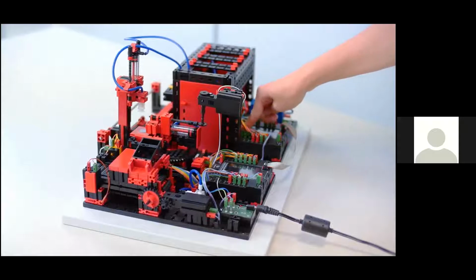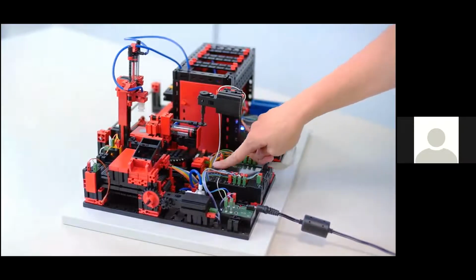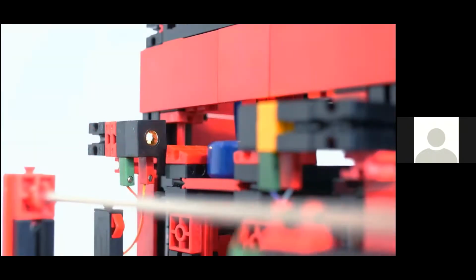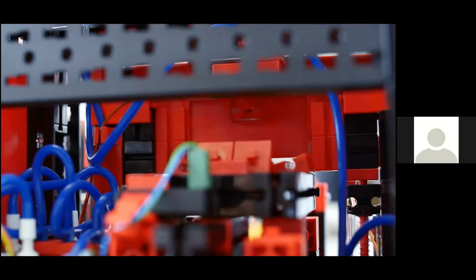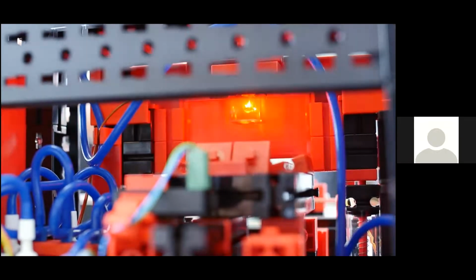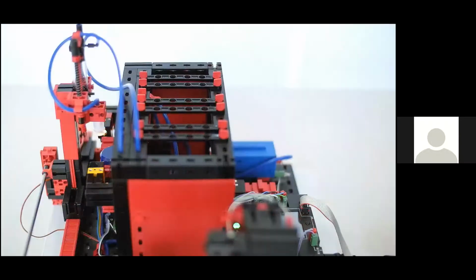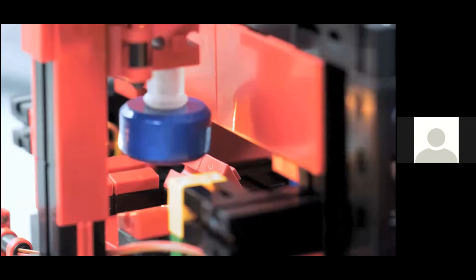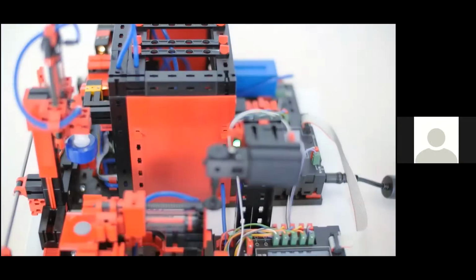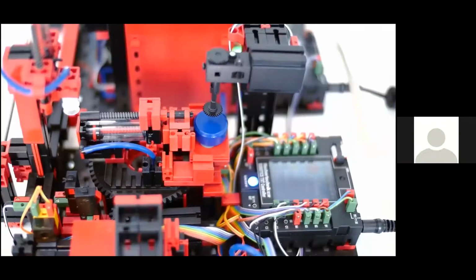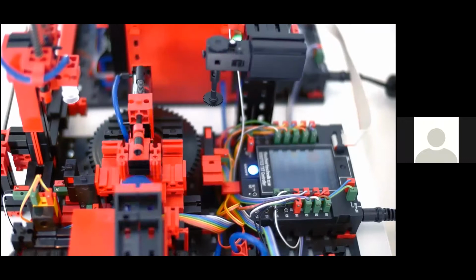The dimensions for the model are approximately 20 by 14 by 12 inches, and it has a weight of just about 11 pounds. Again, the standard version of the model is a 24-volt version for use with the PLC of your choice, which once again has a relay board for motor polarity reversal and both a multi-pin connector with 34 pins and a grid of 2.54 millimeters, as well as additional PCB terminals with push-in connections for all inputs and outputs. The limited edition 9-volt version in this case is connected to 2 Robotics TXT controllers. So in this case, 2 120-volt power adapters will be required for all operation in addition to what comes in the box.